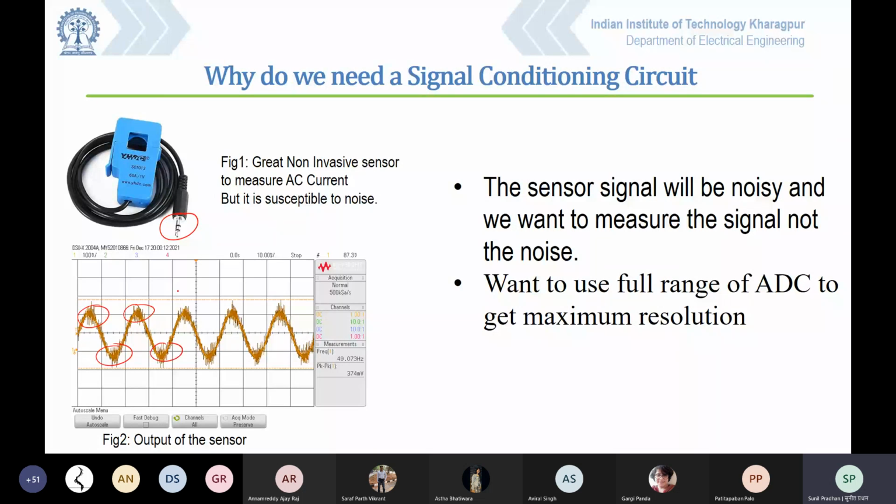And in addition to it, you can see what the peak to peak voltage range is. So this is very less. In this current sensor, it is given that corresponding to 60 ampere current, I am getting 1 volt. And from this DSO measurement, I am getting 374 millivolt. So can you tell what the actual current level will be?